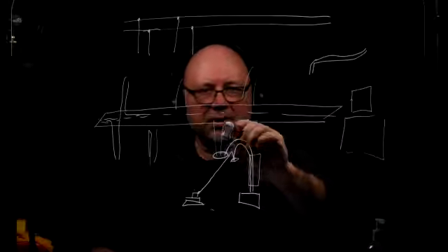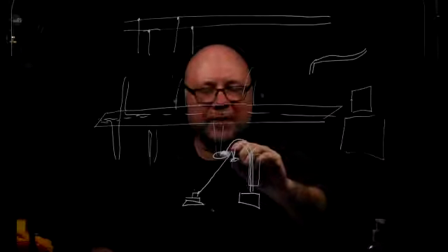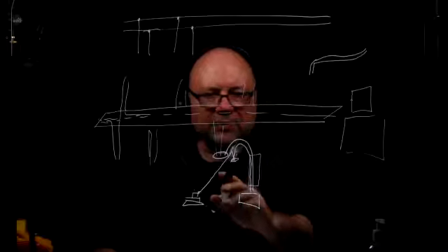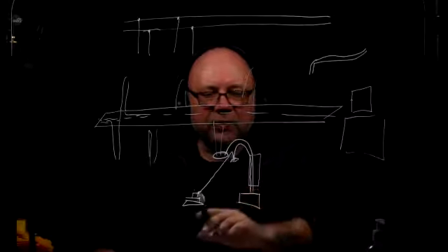The signal that's coming out of the main line is going to be pigtailed or tapped into the main line, and it's going to be providing the signal to the input of the volume control. Out of the output of the volume control, it's going to come back to the same spot, and then it's going to be pigtailed to the wire that's coming out of the speaker.